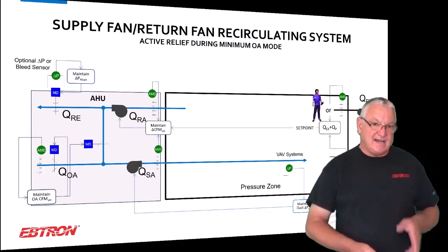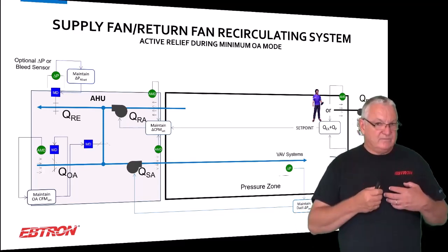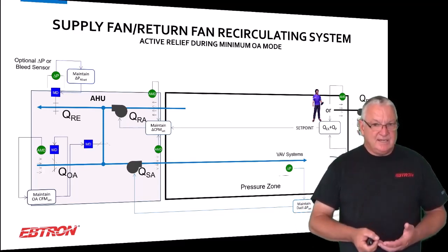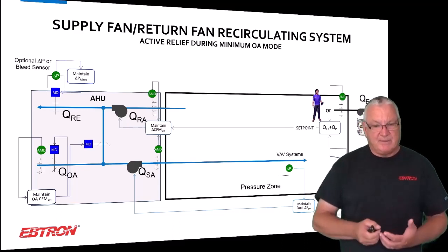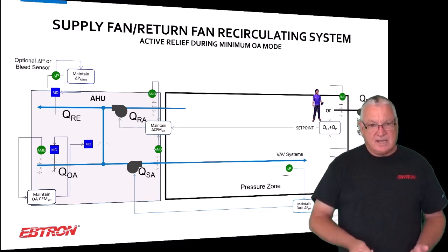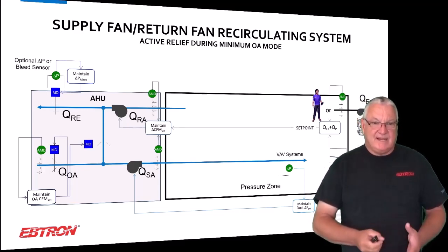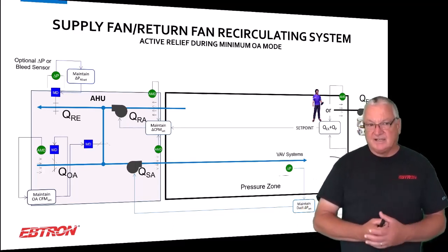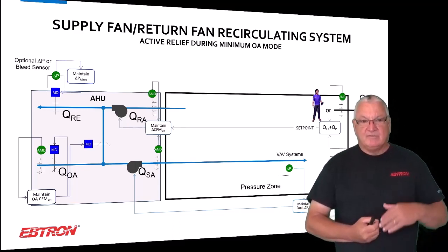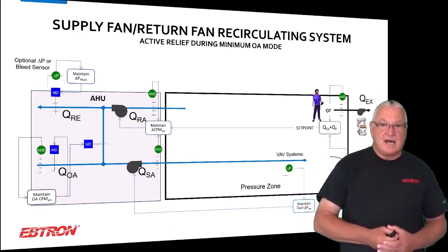So in this case, if it's low occupant density or high occupant density, not big population changes, a fixed outside air set point, basically set that and maintain that. If you're doing DCV, use one of the strategies I talked about to figure out the outside air set point, and then reset the outside air set point. Okay, it's not all that complicated, and it does work well.